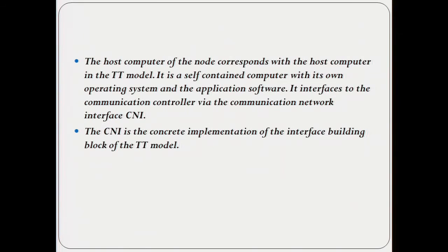Okay. So we said before, the host computer in the TT model is a self-contained computer, meaning that it has its own memory, its own computation, and its own I/O subsystem. And it interfaces with a communication backplane through a communication network interface, which is called CNI. So the CNI is the concrete implementation of the mechanism of communication that we described before.